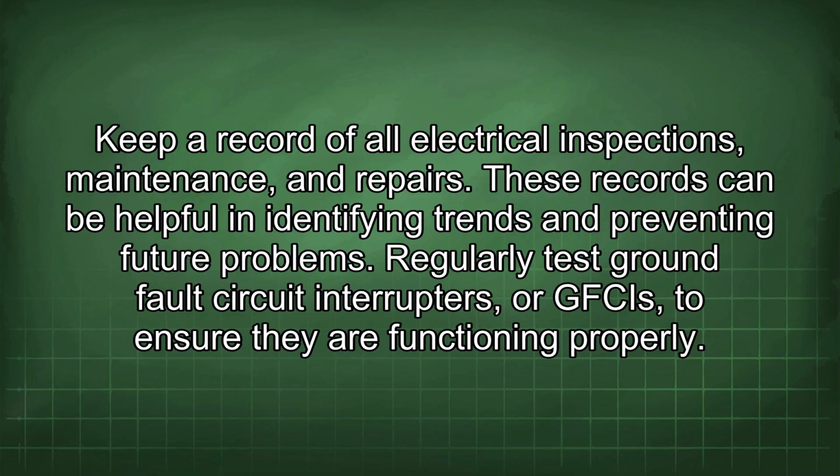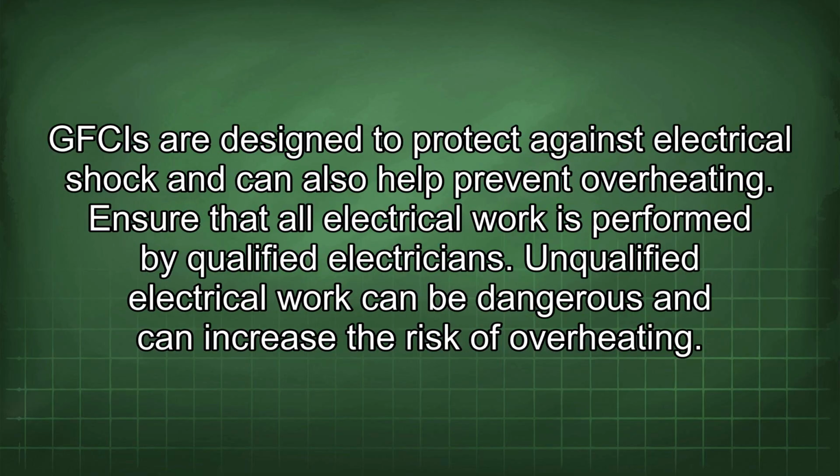Regularly test ground fault circuit interrupters, or GFCIs, to ensure they are functioning properly. GFCIs are designed to protect against electrical shock and can also help prevent overheating. Ensure that all electrical work is performed by qualified electricians. Unqualified electrical work can be dangerous and can increase the risk of overheating.